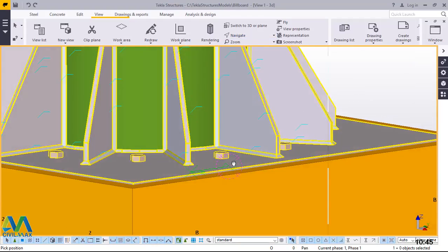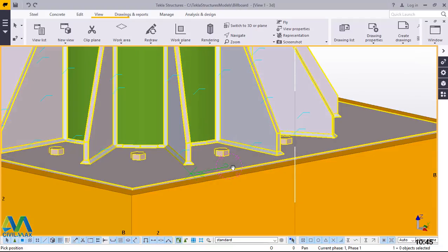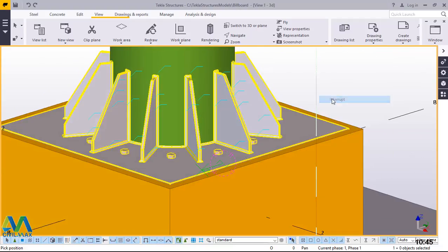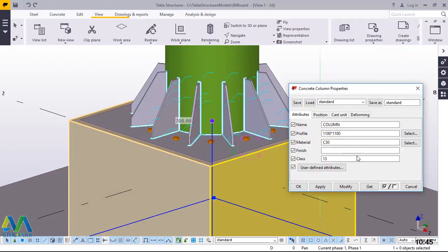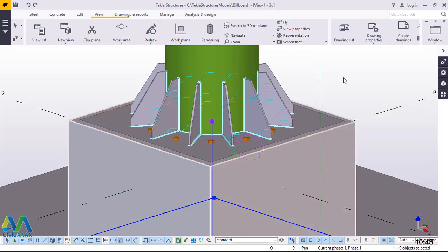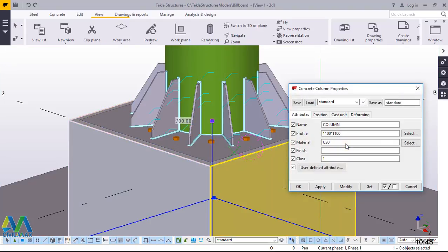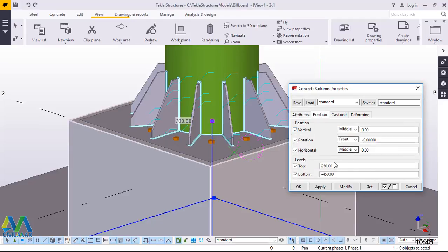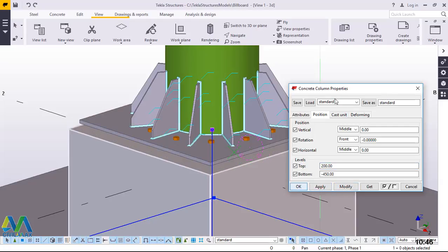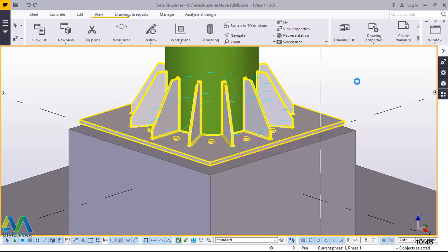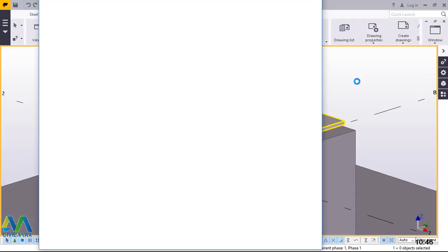Come here and click on that, turn that round. Double click on this member, on this concrete, then change the color, we want color code 1, and apply and accept that. And I would still like to slightly adjust the height to probably 200 right there. Apply and accept. Do we really need grouting? We'll double click on the base plate and give it time to load.